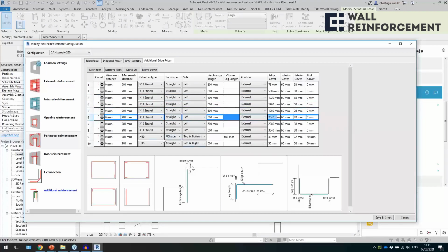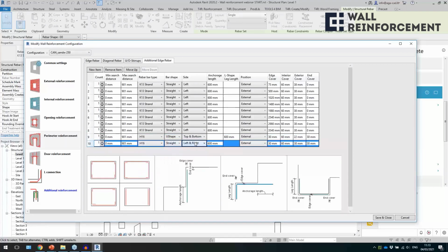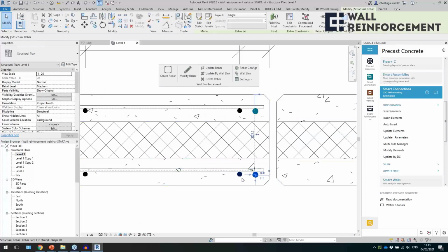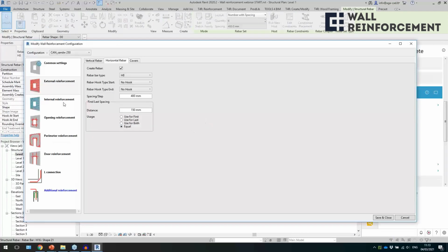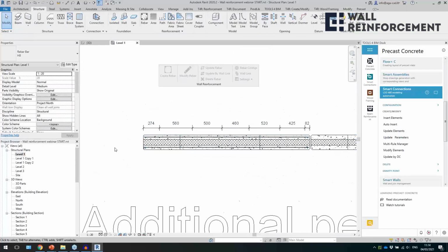And then I have some, so these are, I called these bars like a strand, although they are solid elements, but I think that's good enough. And then I have some U-shaped bar at the top and bottom of the wall, and then straight bars at the left and right, and then just different diameter, right? So that's how I get these vertical bars here, and then I have these strands. And then this horizontal one actually was created with our horizontal rebar settings. So it's also like a combination of reinforcement.